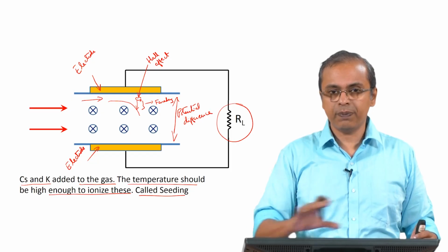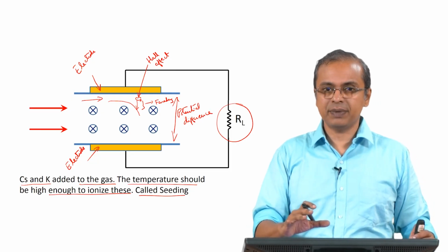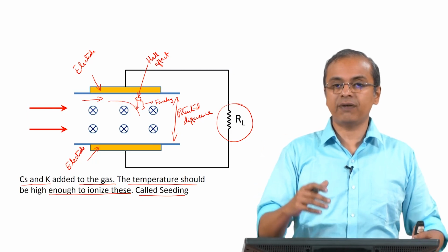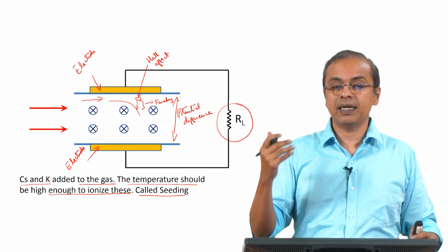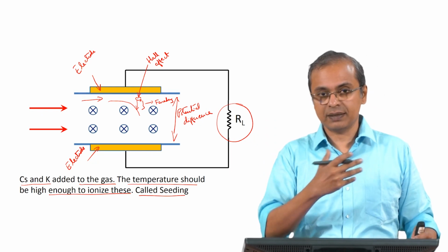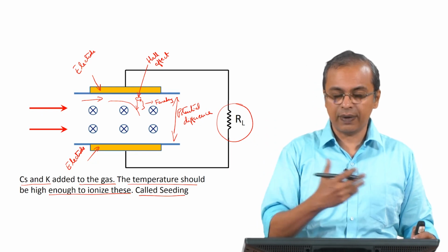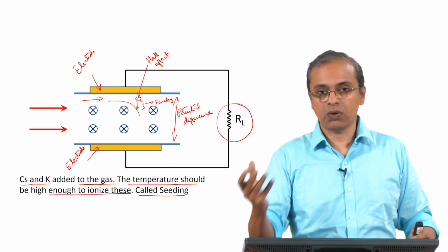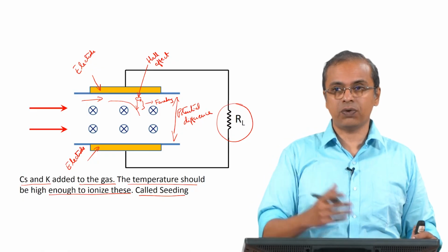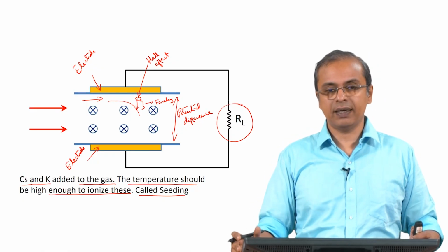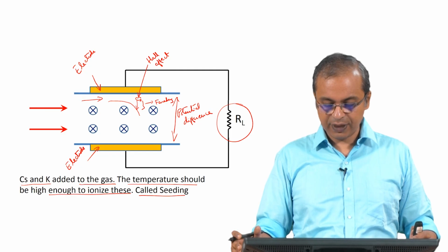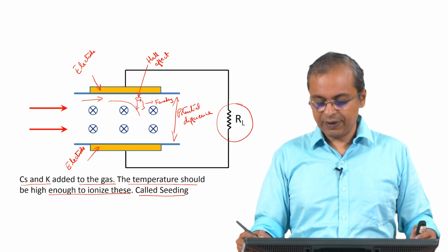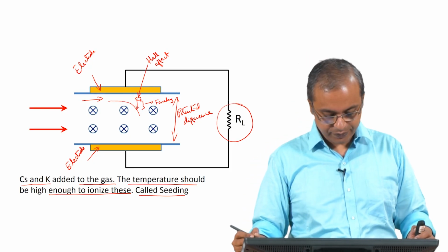when you have a hot gas going, you added something to it, created a plasma, and that plasma is now interacting with this magnetic field, it is generating an electric field, and then both of them are present, and then subsequent atoms that come there become ions, and the electrons have to deal with all of this, or are interacting with all of this. So, it is a fairly complex situation that we have here, but still at the end of it we have a potential which is the potential that we tap, and then we get the load resistor to function.